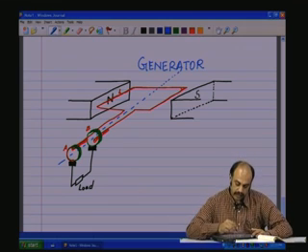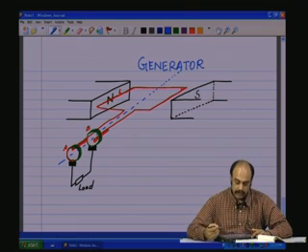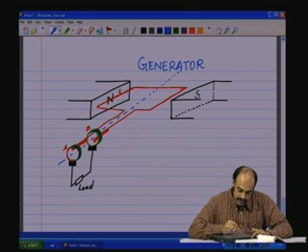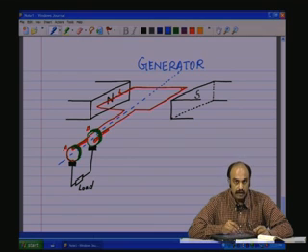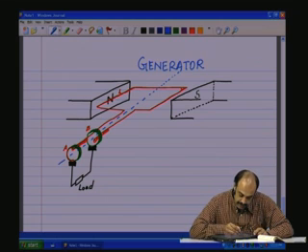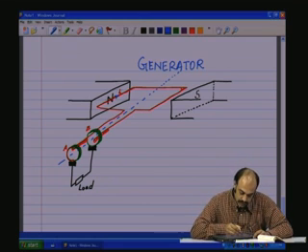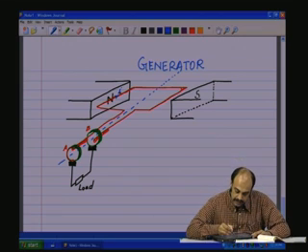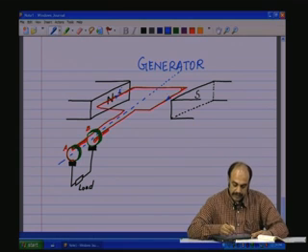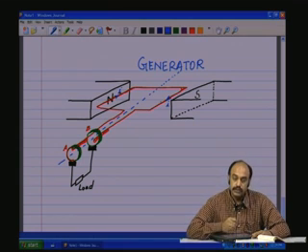So, the whole coil is rotating along the axis, the blue line as shown here. Now, this conductor here, when it is at the north pole, is going to have a positive field, as we saw before, positive max field, and let us say a current I is going to be induced in this direction. This conductor is closest to the south pole, and is going to have negative max field, and a negative current of the other direction, same amplitude, is going to be induced in this.